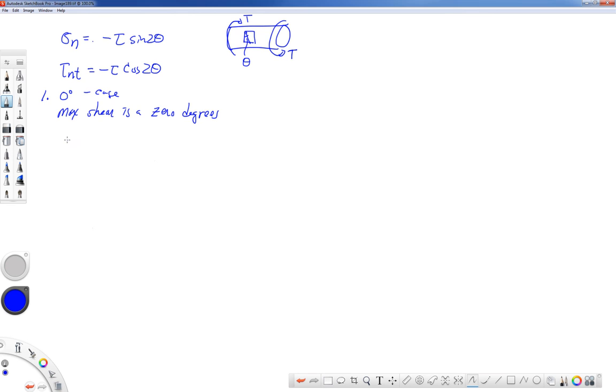The state of stress looks like this picture that I'm going to draw, where we have just shearing stresses. When we put in 0 degrees, the sine of 0 is 0. We don't have any sigma. If I wanted to see what this would look like when it was distorted, then my strains would cause it to take a shape like this.